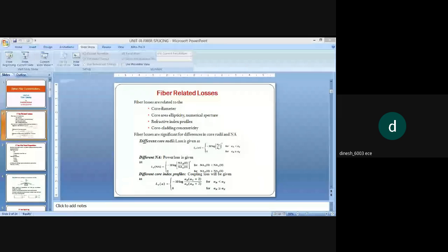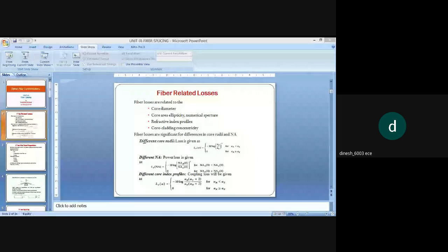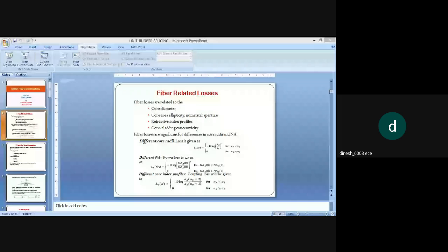If there is any contamination like dust particles, dirt, or coating residues on the fiber or present in the V groove, it can lead to bad fiber positioning, lead to fiber misalignment, which is lateral misalignment, and can influence the fusion process extremely badly.